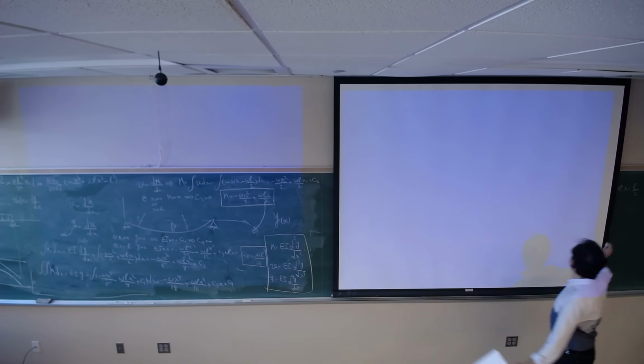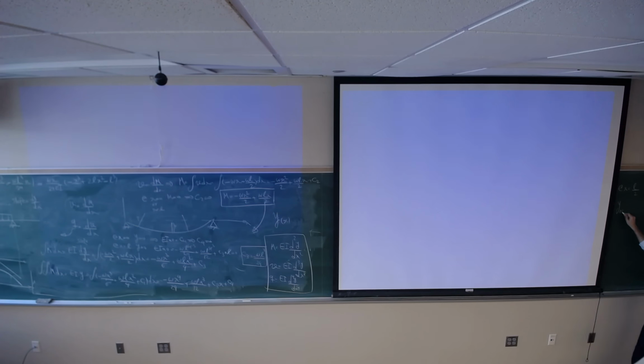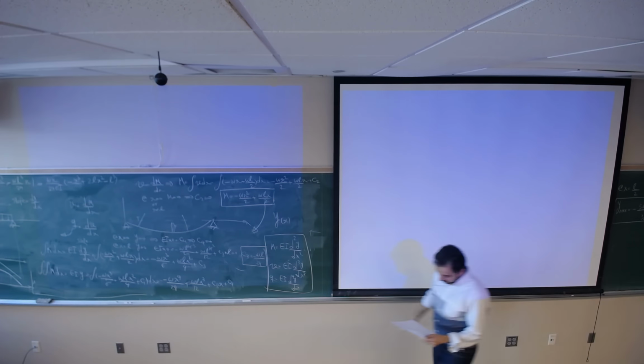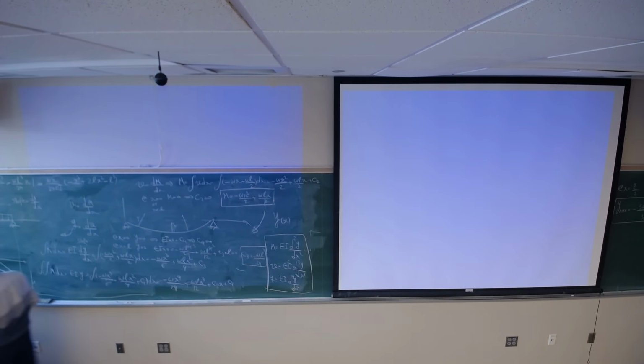My maximum deflection is negative 5wL^4 divided by 384EI. I just plugged in x equals L over 2. And this is just for the beam which is under this type of loading.